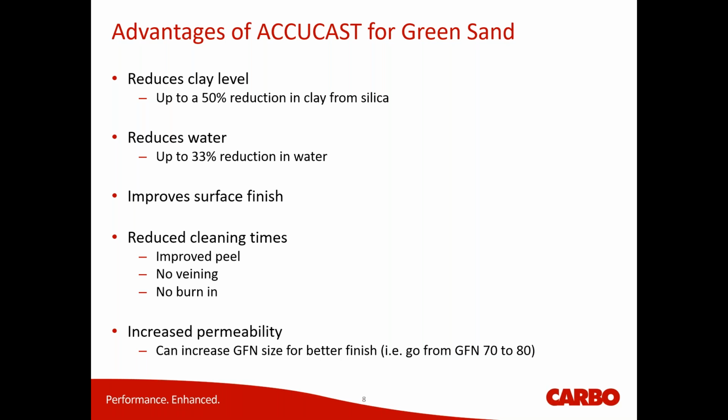Reduced cleaning times was the next thing. So the big item I want to bring up there is the peel. That's the big comment we hear from everybody that's running green sand with our material: the peel is fantastic. Literally, before with silica, any part with an inside cavity, they'd have to bang on it and do all this stuff to get the material out. With ours now, you turn it over and you hit it once and everything just falls out.